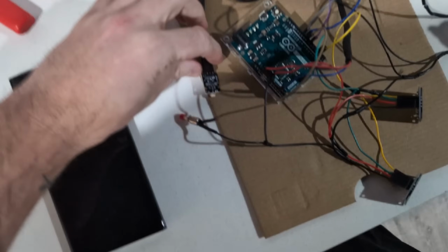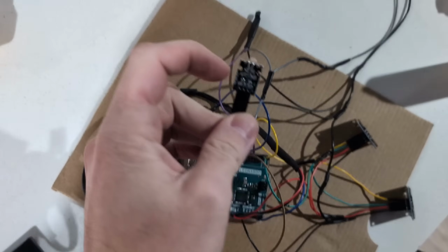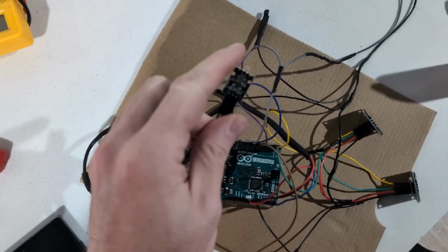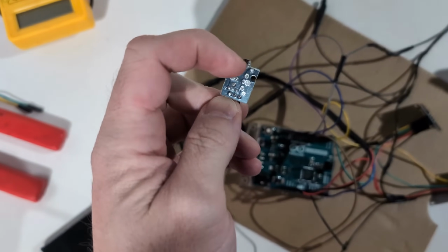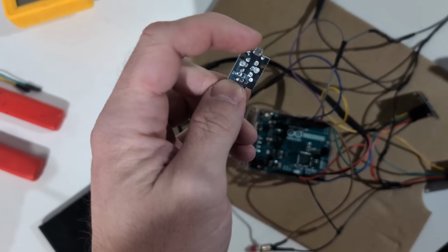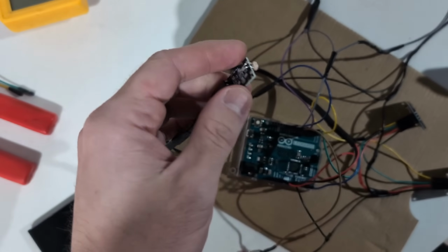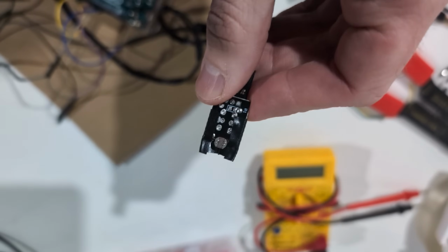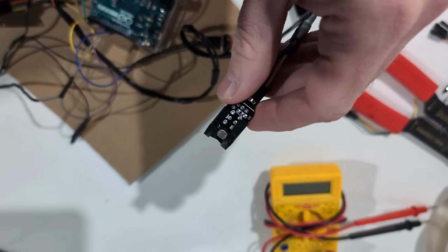Now for the photodiode, it would probably be a good idea, if you're not going to be making a custom housing, to put some black electrical tape out the back, mainly because we don't want any external light to get into the sensor. So that's the sensor right there that'll pick up any changes in a light flash. And we've got to make sure we've got no other light getting to that so we can get accurate readings. So I've just done a quick dodgy job. Should do the job for now. You guys will probably be able to do a better job.